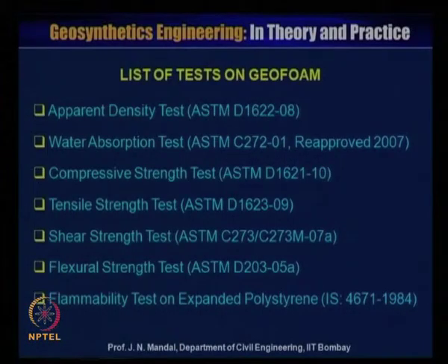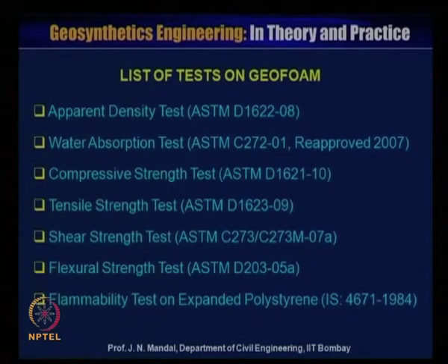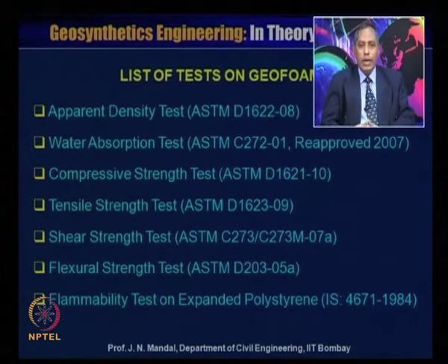Here I will first discuss the apparent density test, ASTM D1622-08, and the water absorption test. As you know, geofoam material may absorb water, and there is a certain limit on the water it may absorb, otherwise you cannot use this material for infrastructure. So, the water absorption test is also very important. This is as per ASTM C272-01, approved in 2007.